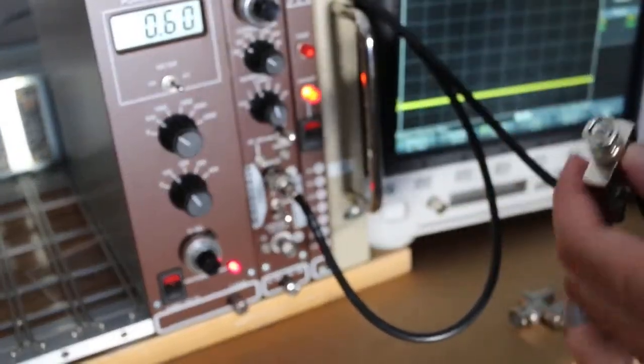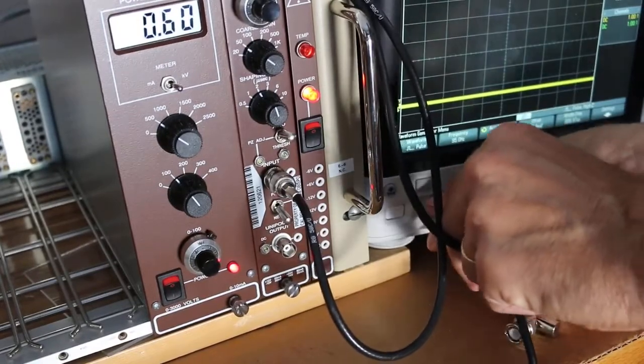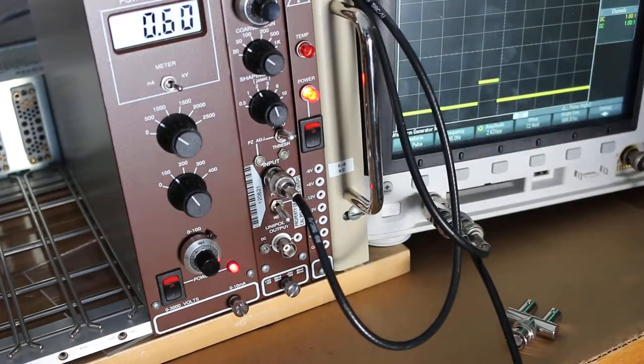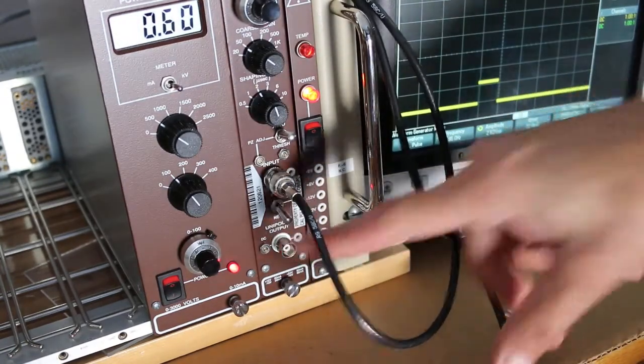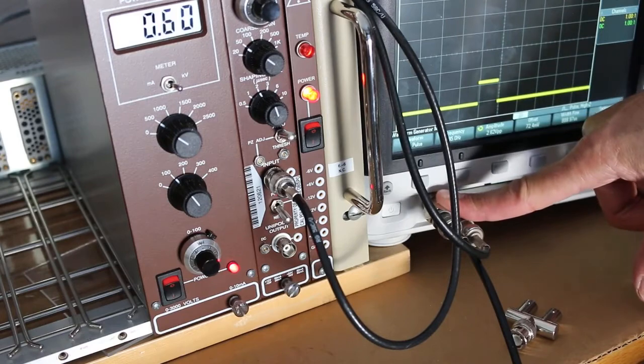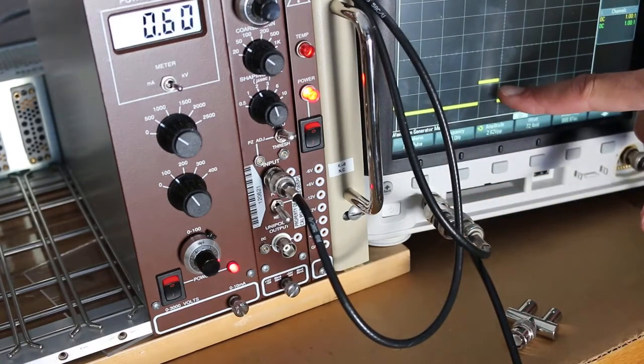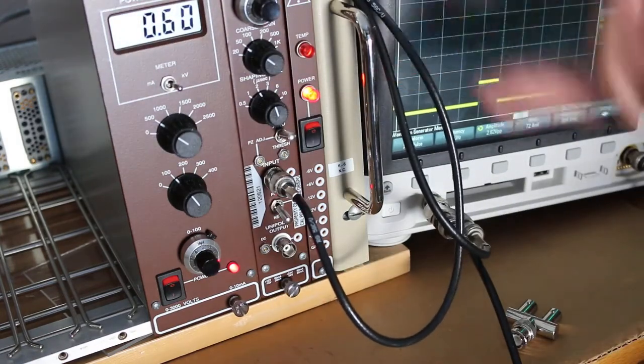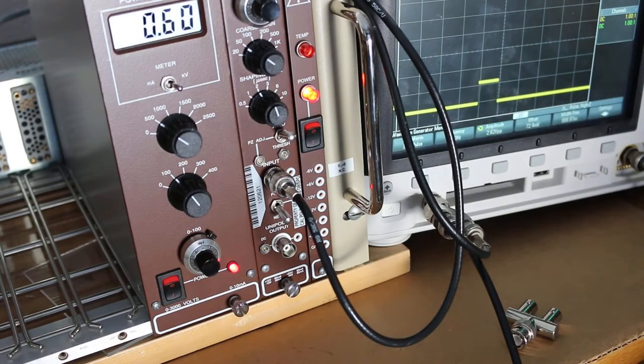I'm going to take this and plug it directly into the waveform generator itself, like that. So instead of having the gamma ray amplifier as the output, I'm going to use that wave generator as the output. I still see the pulse on the oscilloscope, but now I'm also piping it over to the data acquisition software on that other cable. I hope you understand what I'm doing here: by turning this knob, I can change the amplitude of the pulse. You can see it changing on the screen right there. And when it changes, I can send a variable voltage into the multi-channel analyzer to see exactly what it does.